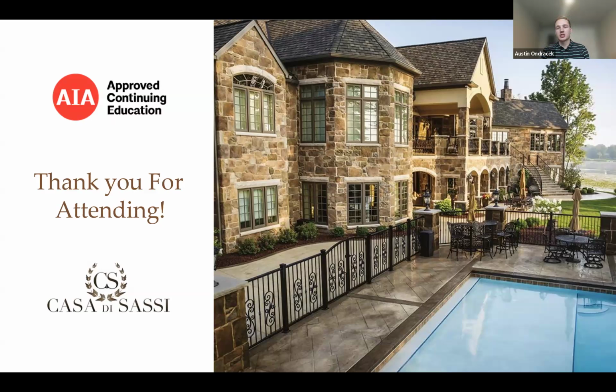If it's an interior application, you're probably fine, and you're not going to have things like the rust that I mentioned happen to the lath. But if it's an exterior use, in the elements, in maybe a harsher climate, I would stick to galvanized metal lath as a best practice and what CMHA has given their stamp of approval for.